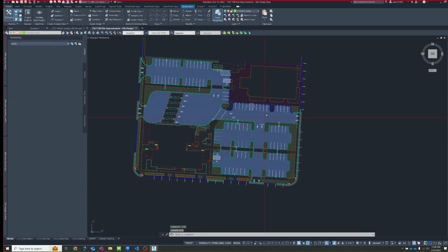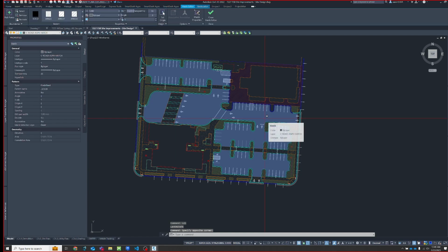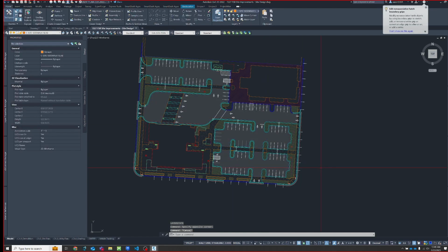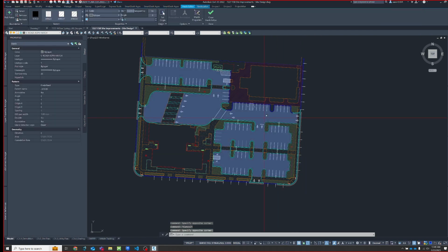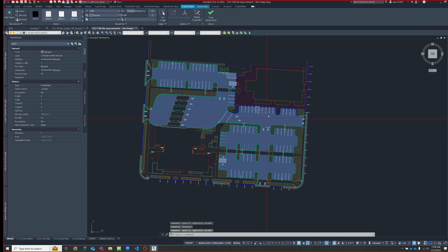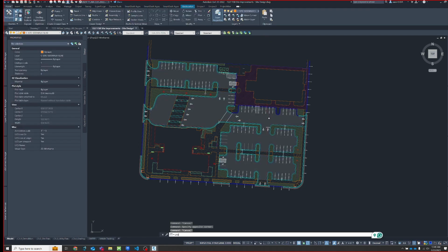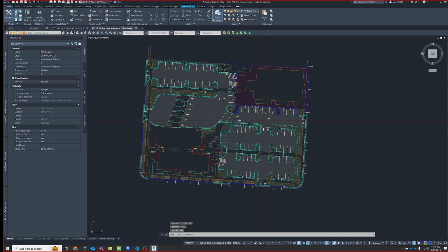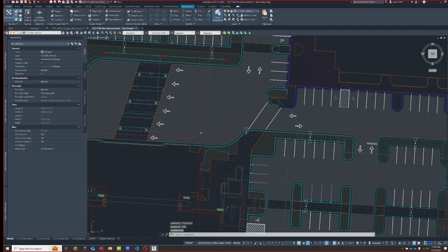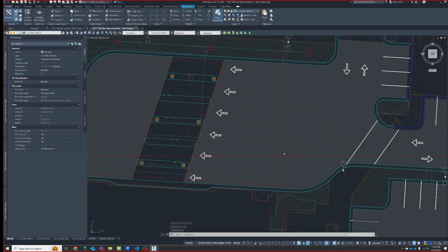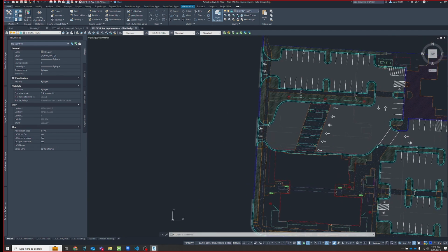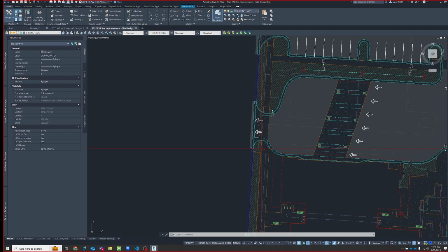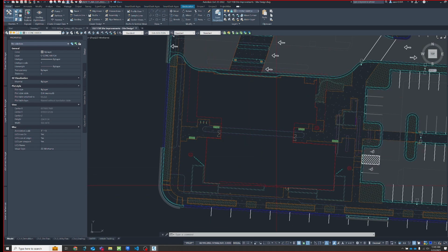Sometimes I turn the hatches on or certain line work or not. This one had pretty much every layer I needed for most edits. It has the layers of the hatches locked because they like to act up a lot. So I lock them so I can't delete them or move them by accident. And if I go to this 2D, it turns on everything inside the site that's existing for my sitemap in the XREF, because there was a ton of demo integrating with curbs and stuff with existing to proposed. This layer state helped me look at that a lot.